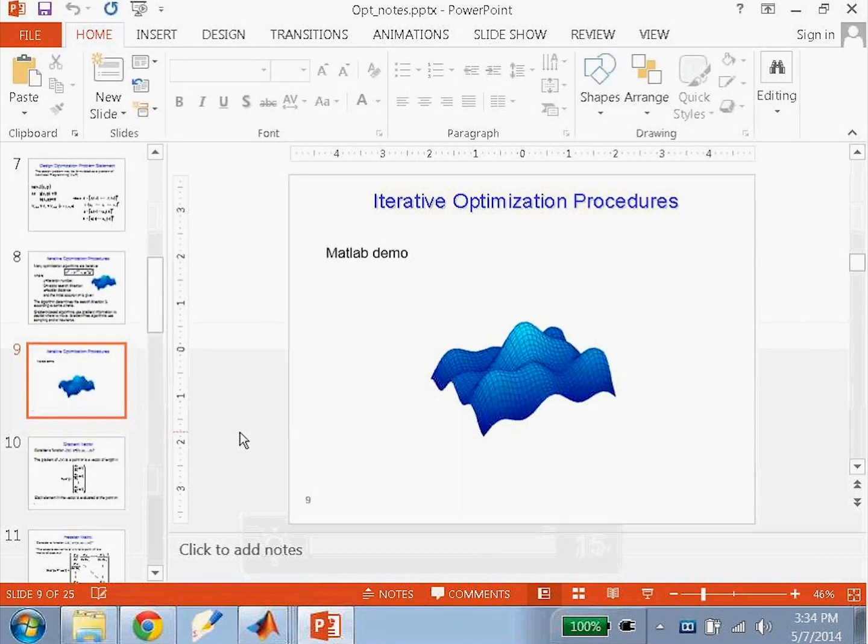So it's all taken care of because we're not sampling. We're actually measuring the gradient. We're doing something different here, right? We're moving through the landscape. We're not sampling and then trying to say how this variable relates to this one. We're actually just looking for an optimum solution. So it's a different thing. Whatever interactions are there, how are they reflected? They're reflected in the shape of the landscape. The shape the landscape takes is a manifestation of how the design variables relate to each other and how they affect the objective.